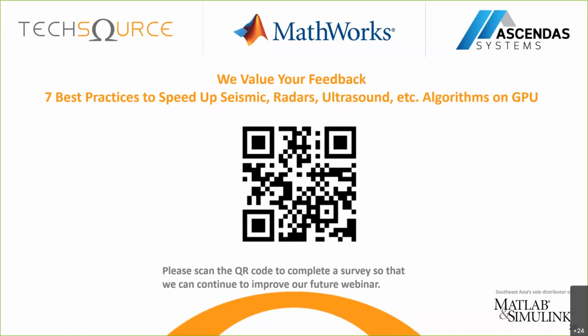If you can get away with Parallel Computing Toolbox, that overhead is still there, but it is handled by the MATLAB engine inherently, so that is usually a little bit faster. To make a long answer short, the Parallel Computing Toolbox should be faster for a couple of operations which you can do with GPU arrays. But for the things I'm doing, we have to use a MEX file. So thank you for asking that question.